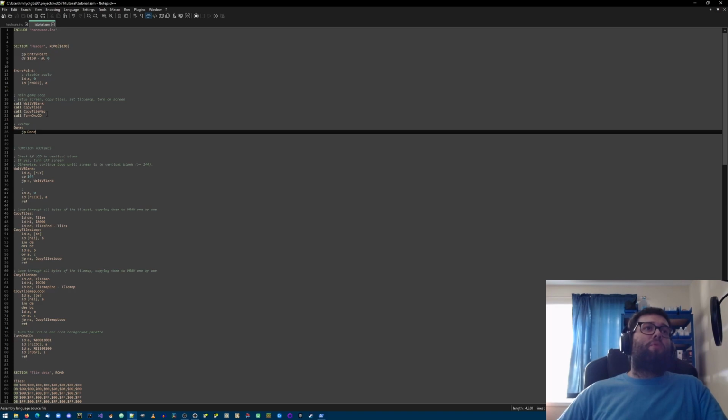If this is on a real Game Boy, you can actually damage the hardware. In fact, historically, Nintendo would deny the production of any games from publishers or game developers who did not adhere to these protocols. So the assembly code had to actually turn off the screen in a safe way, meaning it had to be turned off during this VBlank period. So we'll make that call to a routine that does that for us.